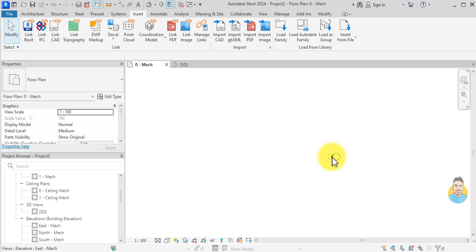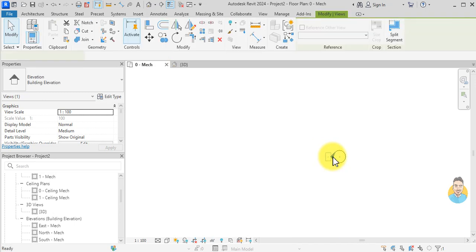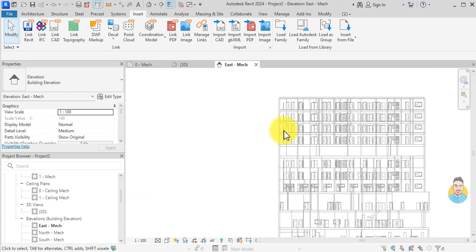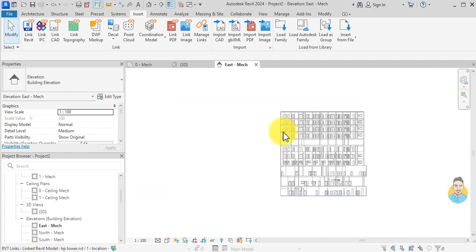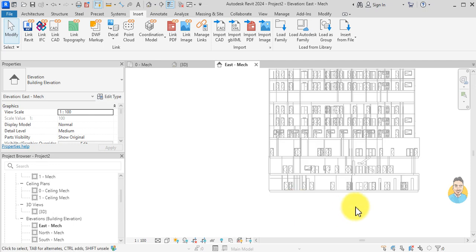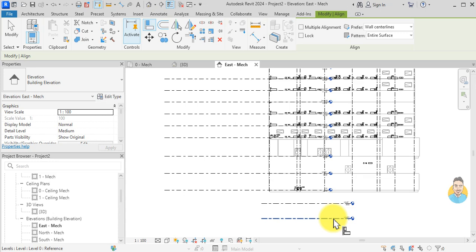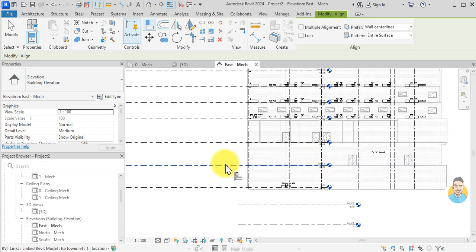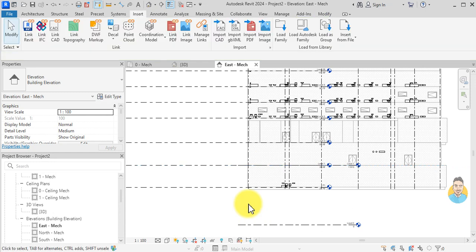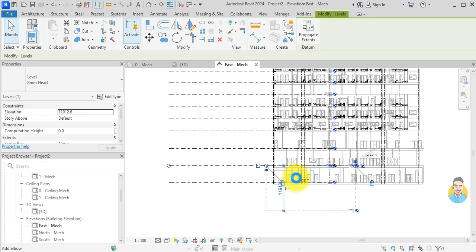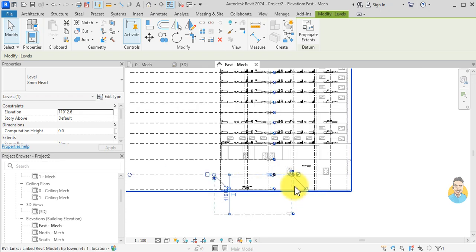So I will double click on this arrow, and I will go to the levels, and then I will copy the levels from the architect. First, I will align the 2 levels that we have. I'll press AL for align, and then I click the target first, and then the level that we will move. Then I click, and I will drag it all the way to the right.